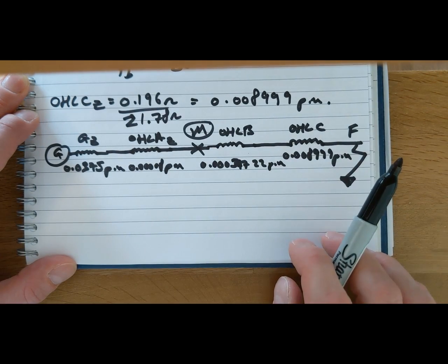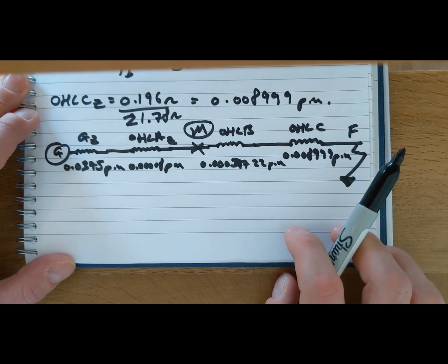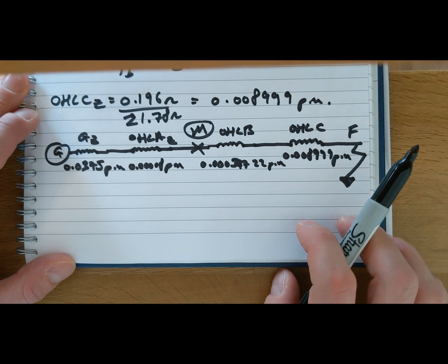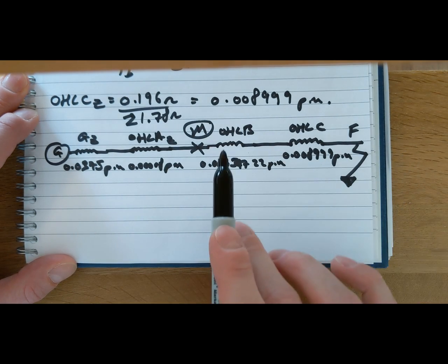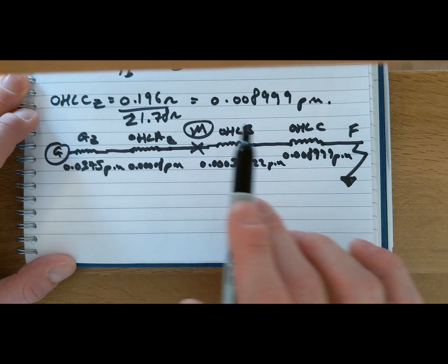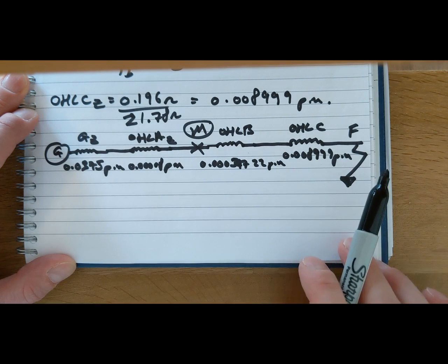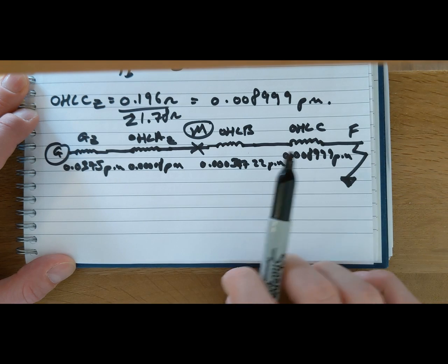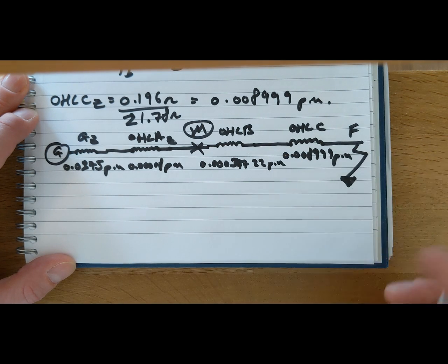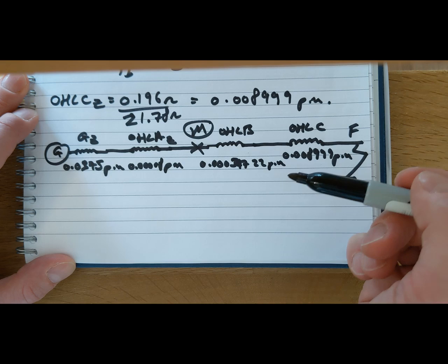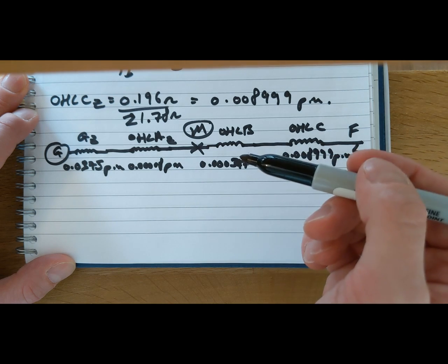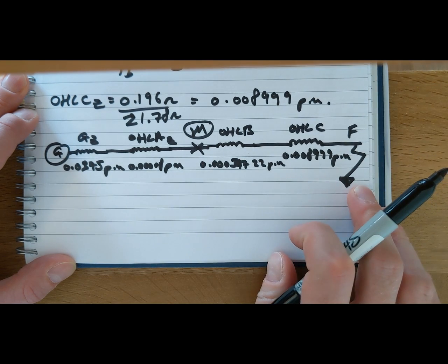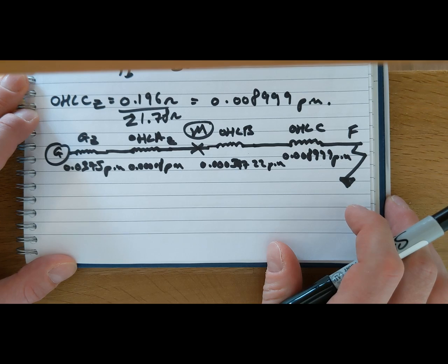And that's why the per unit system is used in power systems engineering, because it saves on a lot of laborious calculations. All these laborious calculations of converting endlessly through the transformers now can just be completely forgotten about as long as we do our calculations in the per unit system. And then all we have to do once we've completed our calculations is convert these per unit values into real values. One little simple basic step.